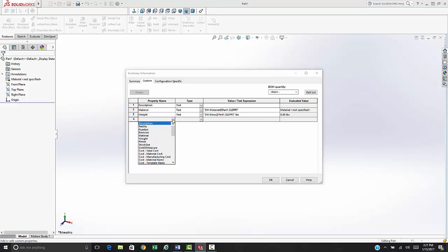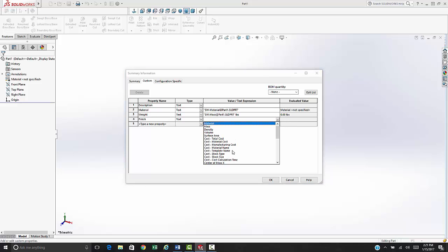You can select anything else on here you like to add. I'll also add a finish on there if I'm doing an anodize or a nickel plating. I'll come in and change all this. There's no finish callout here, but you can just type in here if you're going to do an anodize, and whether type 2, type 3, and the color. You can add all that information in here, and that will show up on your drawing.